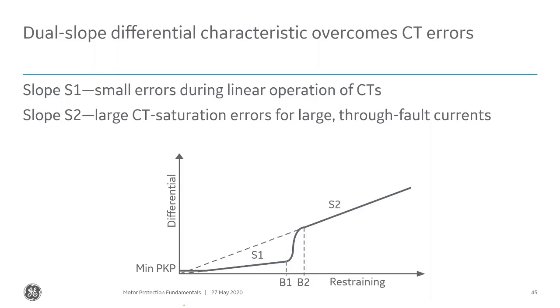The reason we do all that is because a phase-to-phase fault typically provides a whole lot more fault current, which means a whole lot more damage than a phase-to-ground fault. And since it is so much more damaging, we want to make sure that we protect for that, and we get that off of our system as fast as possible. Now, one of the ways that we can do that for really large motors that we want to protect very well is with a differential.